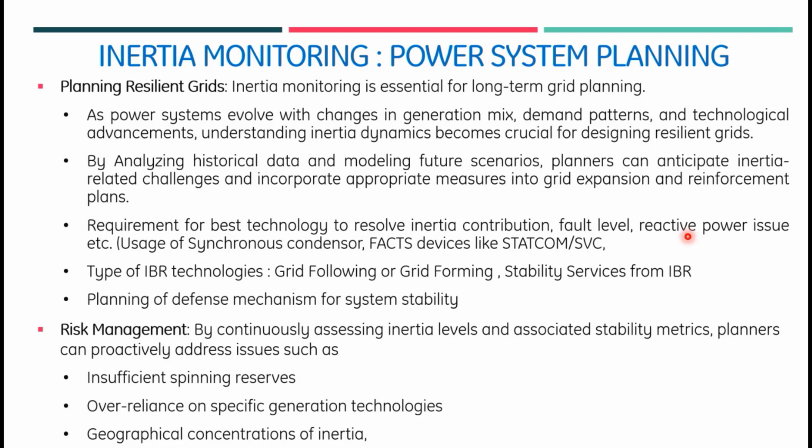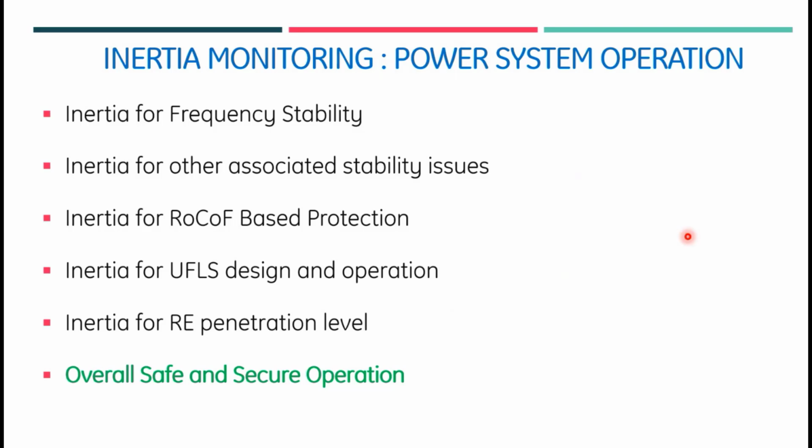So that's where the concept of power system global inertia has come to regional inertia, depending upon how much inertia is available in one particular area. And in operation, we discussed that inertia monitoring is very crucial for frequency stability.